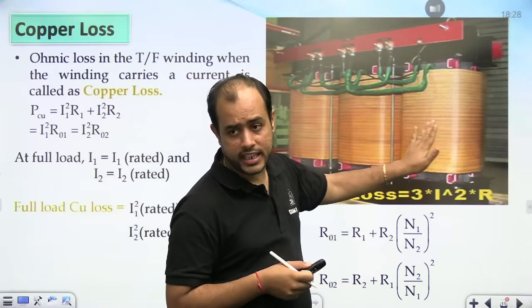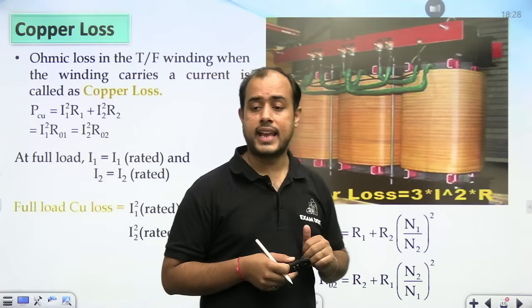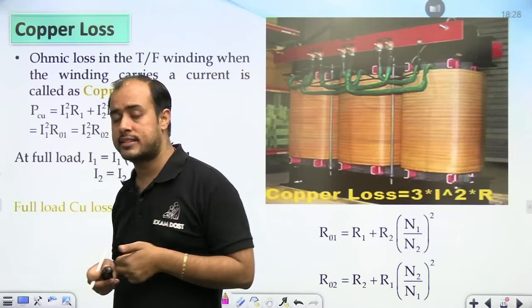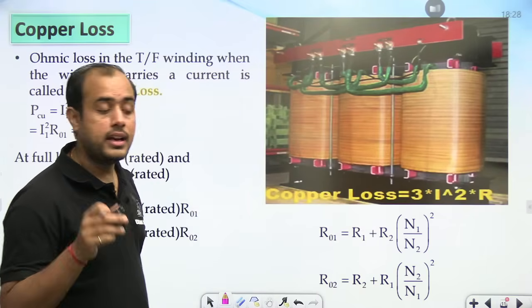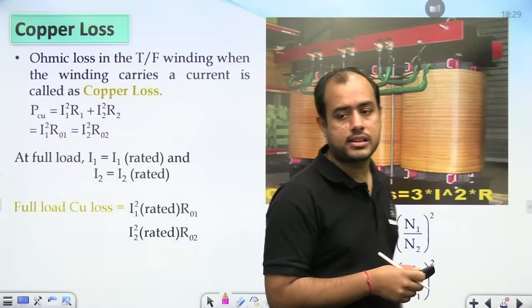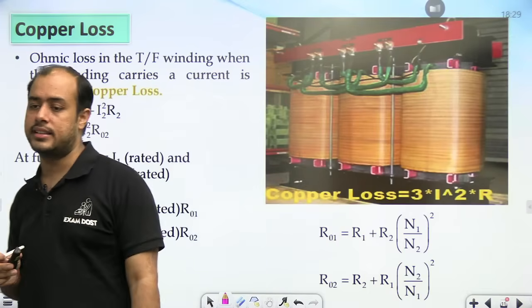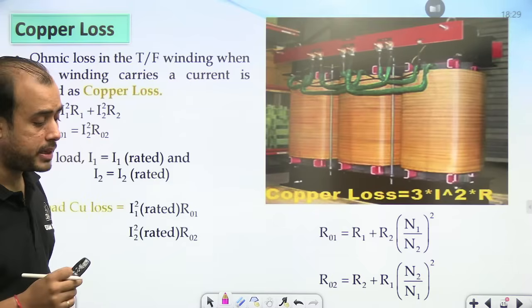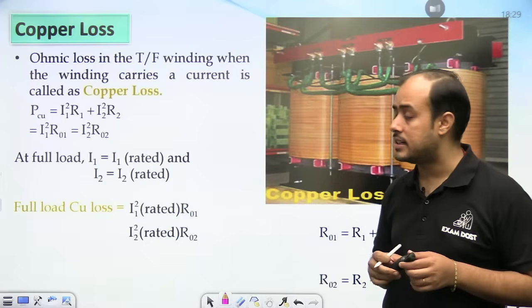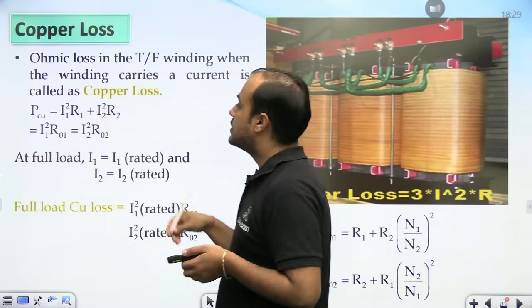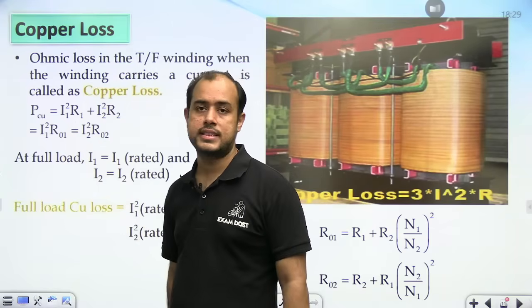यहाँ तीन वाइंडिंग है थ्री फेज ट्रांसफॉर्मर की, तीनों कॉपर से बनी है. तो when they carry a current, जब इनमें करंट बहेगा तो एक लॉस आएगा I square R. For three phase, it will be 3I square R. Now beta, when I taught you practical transformer, in that we studied the transformer with winding resistance. उस समय I discussed in detail about the copper loss. So copper loss is the copper loss in primary plus copper loss in secondary.